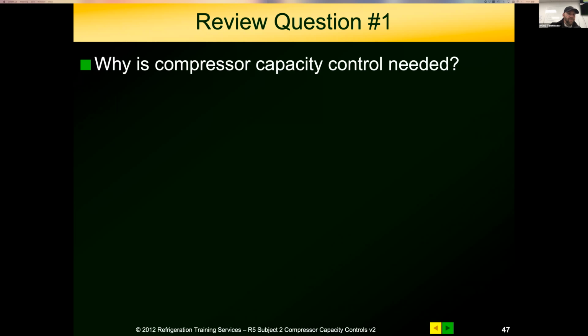We may need to add a liquid injection valve, or we may need to add a desuperheating valve. Copeland makes those Y valves you can strap to the discharge line that will inject refrigerant that we can tie into the liquid line. That will set you apart as a better technician. If you look at an application and you know your superheat's dialed in, you know the case is doing everything it can, but it may have been undersized in the piping, and the customer doesn't want you to run 200 more feet of pipe to reduce that compression ratio, then let's try and put a liquid injection valve on it. That's a lot cheaper repair, and you may be able to make it get by.